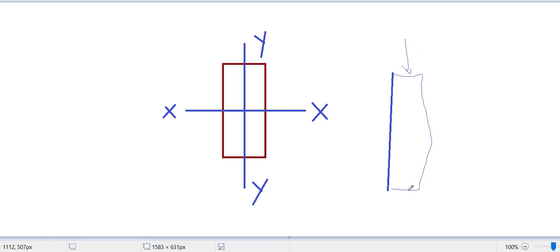So if I apply the load, what will happen? This column will buckle about this way. Why? Because of the geometry, we have less material on this side to resist the buckling this way. But in this way it is very difficult to buckle because there is a lot of material in this way, a geometry factor. So this is the common sense. Technically we say moment of inertia, I. Whichever direction has I minimum, that axis is critical for column buckling.